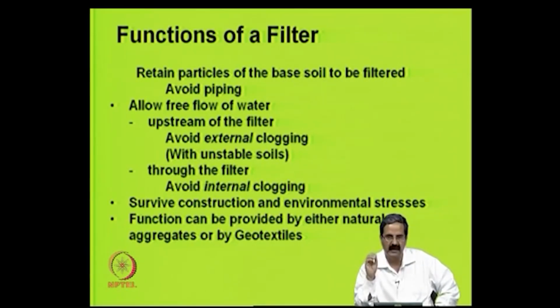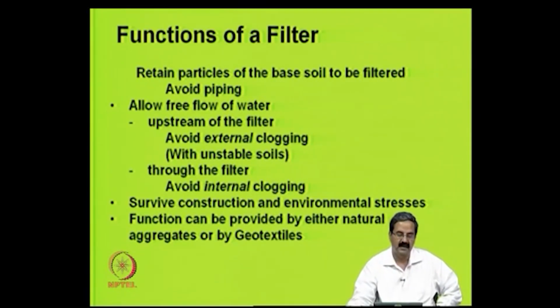So, you would like to have a clean filter, so that only water comes out, but not the soil. Then we should retain the base soil. If the backfill soil starts being removed, then it is a problem, right. You do not want the soil to be lost, you only want water to come out.